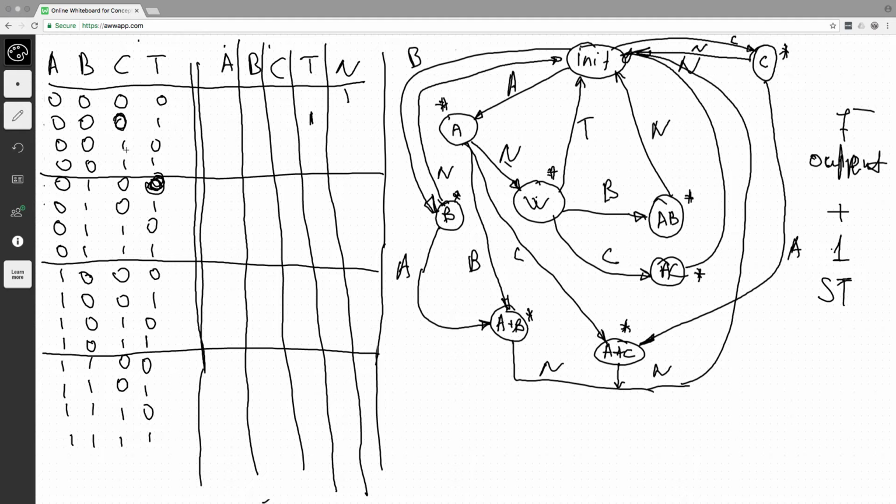Now, when C only is pressed, it is the clear indication that C will be there. When C and timer expired, we cannot say that this signal will be engaged, because we're supposed to stay in this state and wait for either C or the timer, whichever comes first.